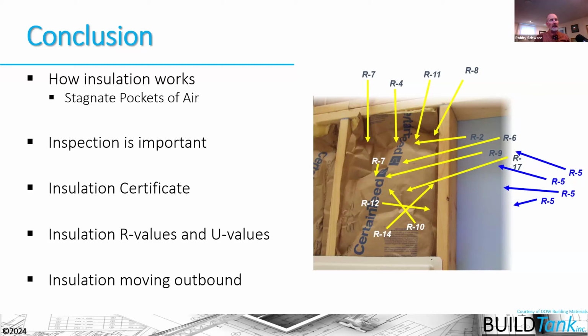We need to begin to rely more and more on the insulation certificate that should be left immediately after the installation of insulation so that we can determine has the R value been achieved, especially in products that aren't labeled, as they don't have an R value mark on them.